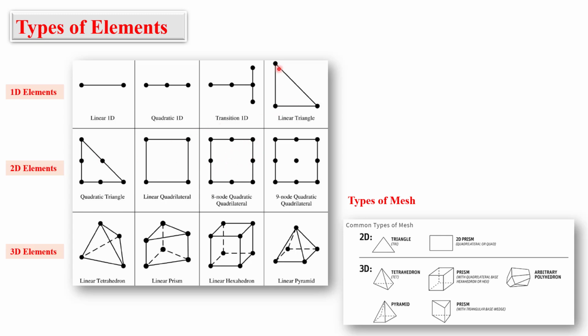If you have 3 nodes in the tria, it is a first order element. If you have 6 nodes, it is a second order element, which can fit complex geometries, but 90% of the simulations are done on first order elements, like the quad elements and the tria elements. Even we have the second order 9-node quadratic elements and 8-node quadrilateral elements. So these are a few 2D elements.